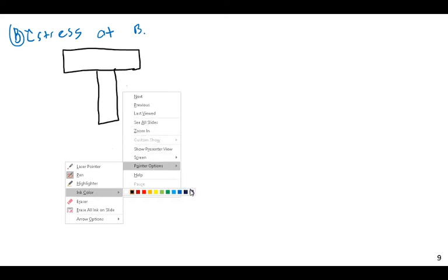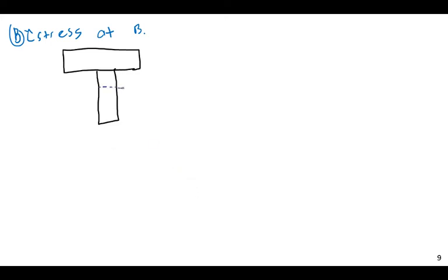So the neutral axis is here, and it's not really important anymore. B is here, and the outward Q is going to be smaller in this direction, so we're going to base it off of this. In other words, the larger the Q, the higher the shear stress. So we're going to take it this way instead of this way.